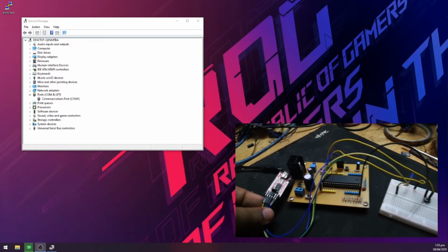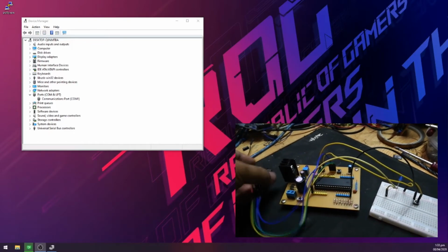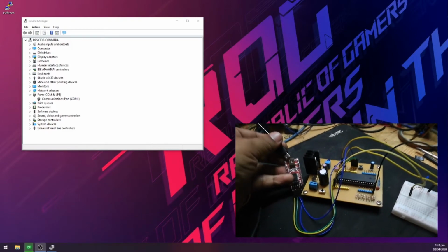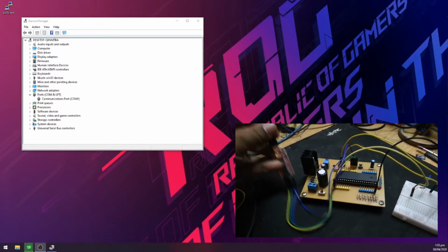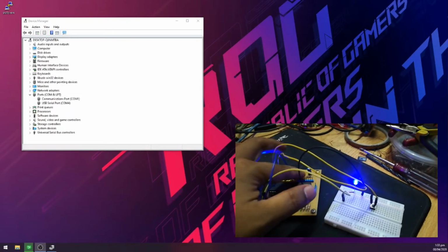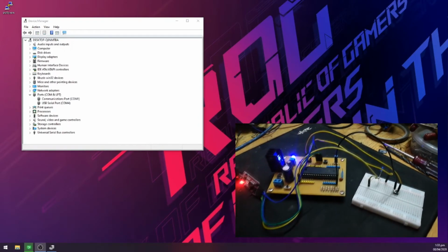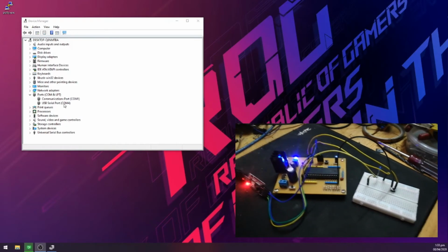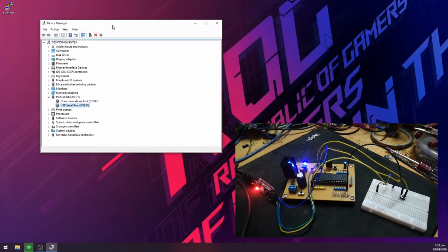Let's see it in actual. We loaded our compiled hex to our board and connected a USB to serial adapter to our board. It will be detected as a COM port in your computer. To test, we use a terminal program such as PuTTY. When you open it, enter the COM port number of the USB to serial adapter in PuTTY. As you can see, a string is received by the computer, and if we press the A on the keyboard, we toggle the LED and send a string.